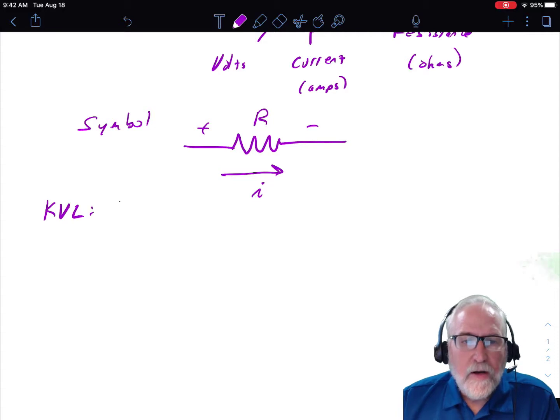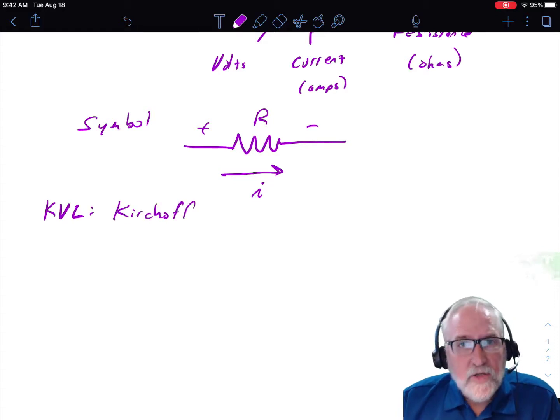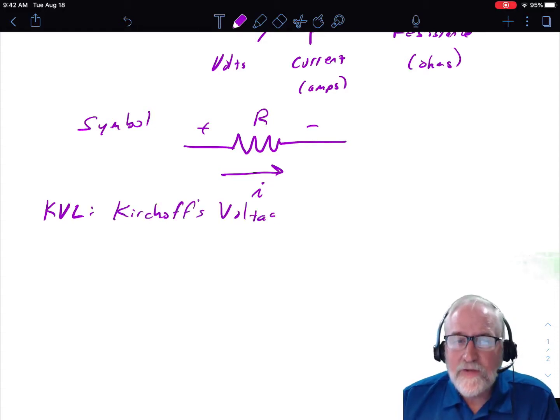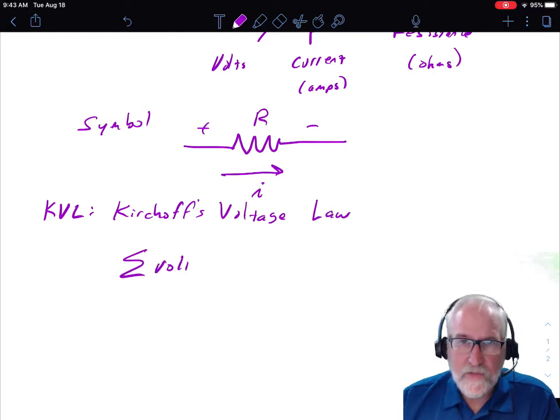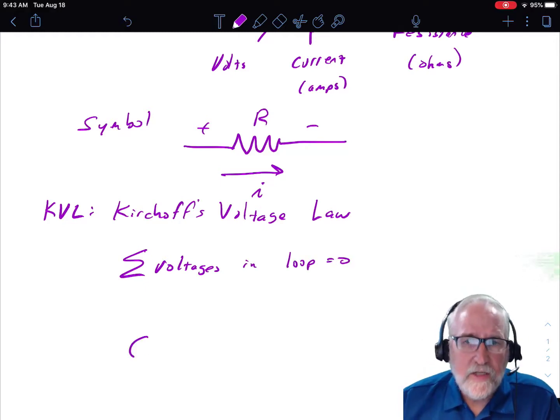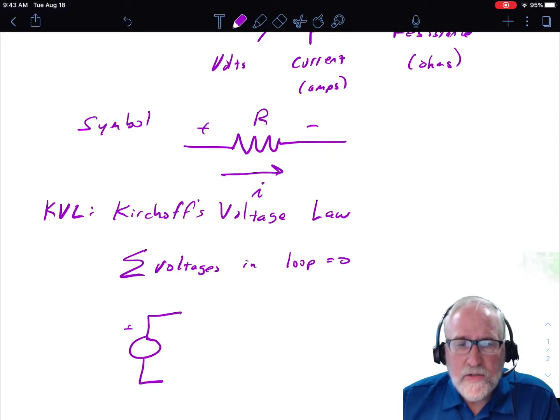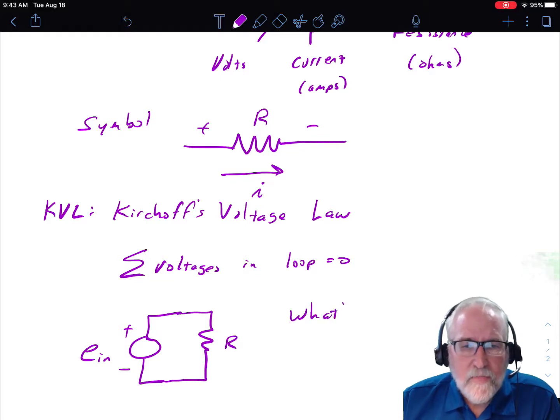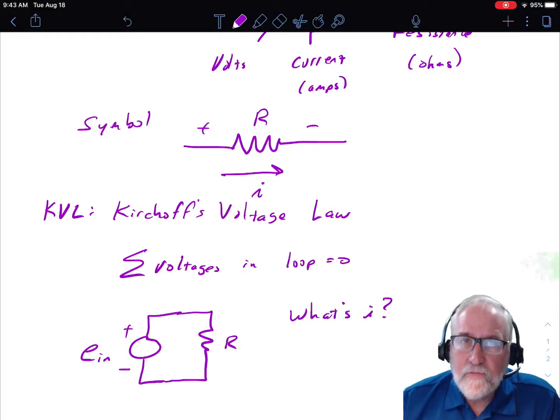into. And then we go into Kirchhoff's voltage law, which is fairly simple. It's sort of the electrical engineering metaphor for Newton's second law. And what it says is the summation of voltage around a closed loop of a circuit has to equal 0. And we'll show how this applies in a very simple experiment with a constant voltage source and a resistance, and that creates a current flowing through our loop.